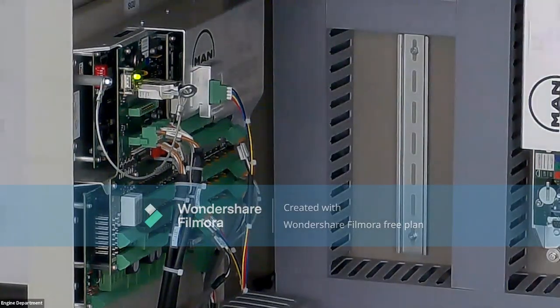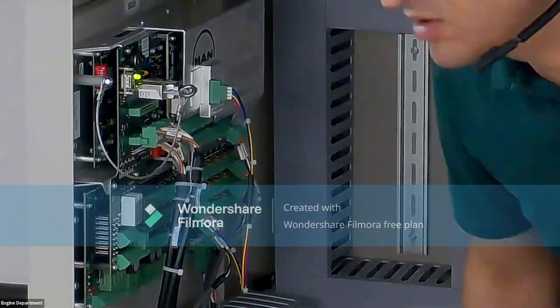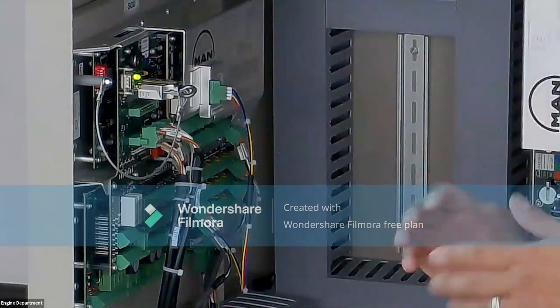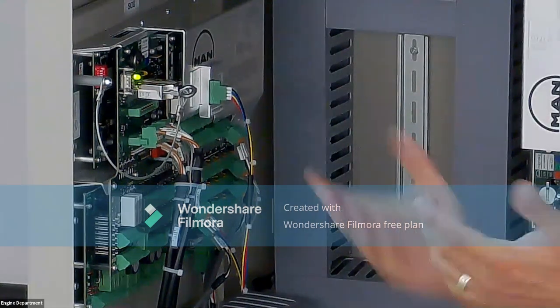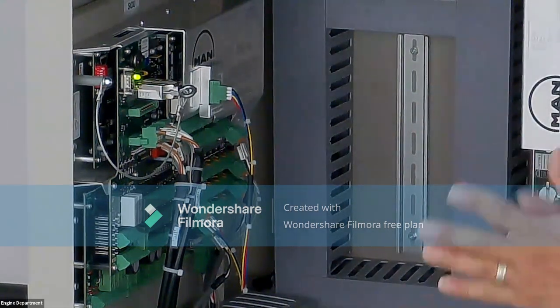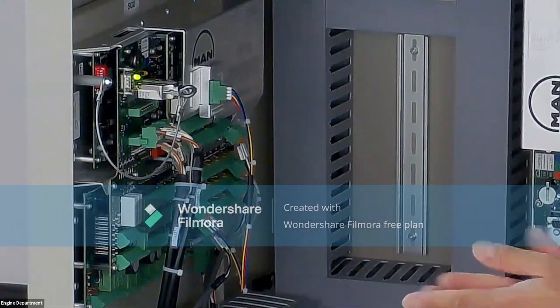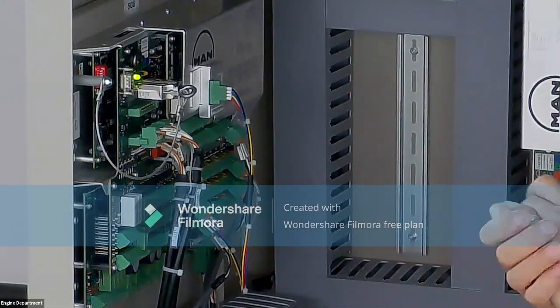Gentlemen, as I told you, we receive an alarm: MPC scavenge control unit failure. We are checking the LED condition. Fatal error, the LED is in red. Our LED now is in green. This means it's operating normally, but let's assume for the sake of the exercise that this is in a red condition. So it's required to replace the MPC.